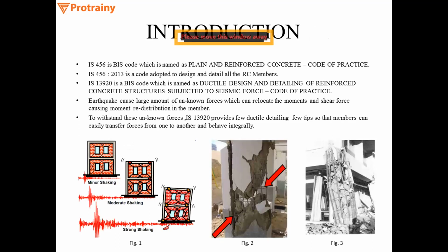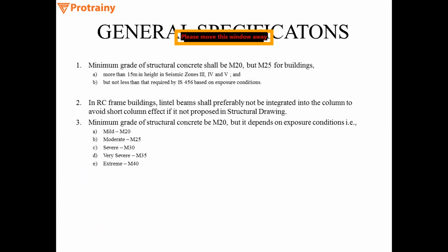That was one of the reasons for shear failure that I was telling you about. That could be a reason for the shear failure. So in mountain areas, short column effect is dominant.